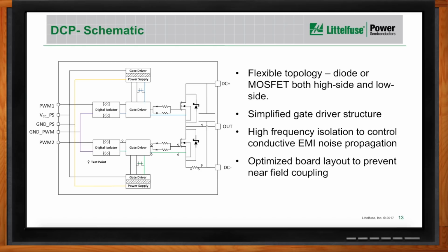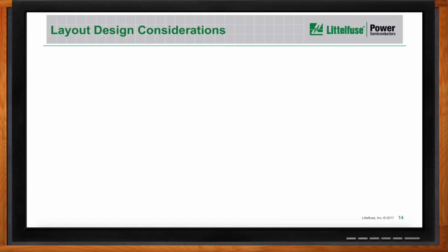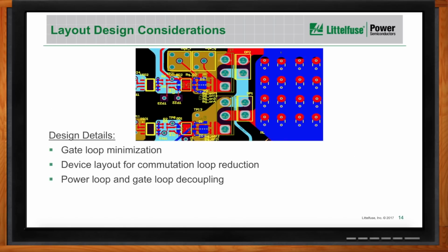All right, so when I want to kick the training wheels off and design my own board, what do I really need to think about? Okay, several details about this board. One is the layout design, because this may not be a very important feature for silicon IGBT design, but it is very important for silicon carbide MOSFET design.